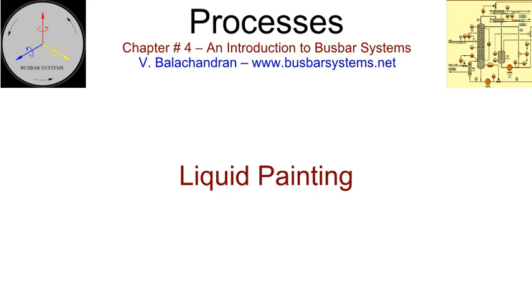For aluminium, etched primer is recommended. This bites into the metal and forms a good interface between the surface and the final shade of paint. Finished coat is applied by a spray gun. Enamel and epoxy are two different types of paints that are most popular in the bus industry. Paint industry is highly advanced and matured.